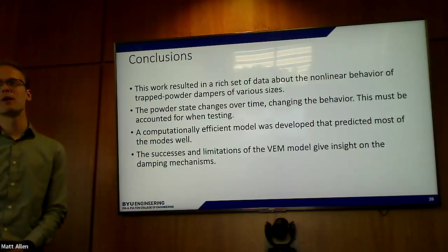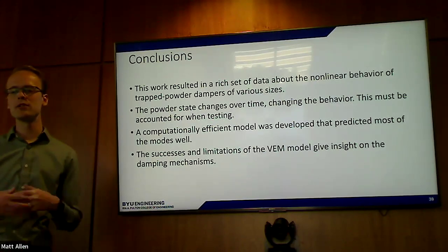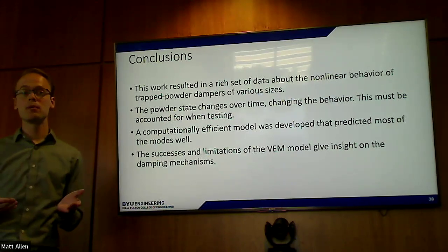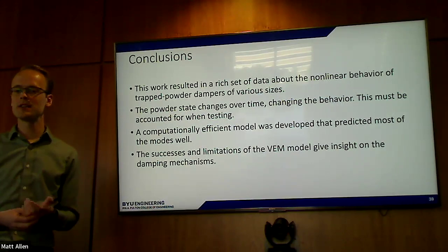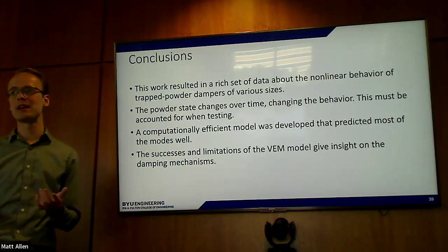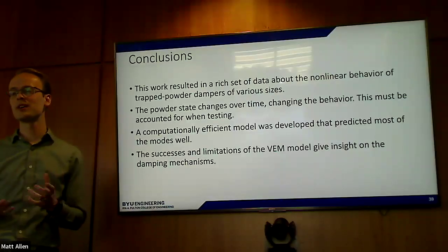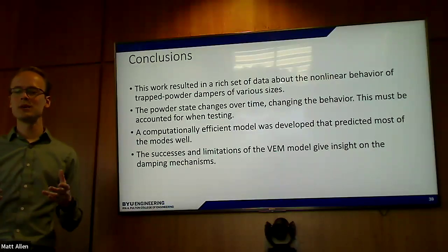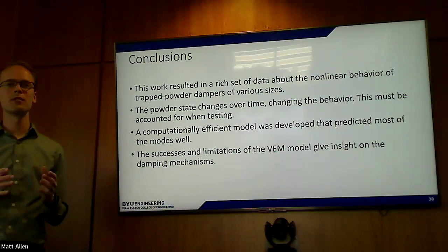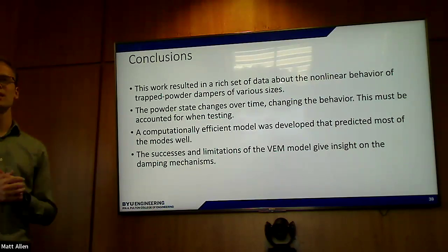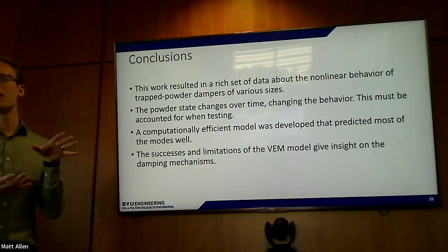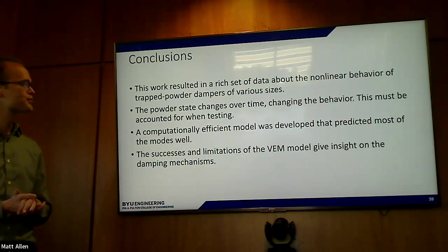In the worst case scenario, imagine you make a part and you test it and you measure it to have 1% damping, but then you take it out into the field and 6 months later, the powder is settled and now it has 0.1% damping and then it's vibrating 10 times as much. So we really want to make sure that people who are designing these parts are aware of this time varying component that the system can change over time. So you need to make sure that you capture the upper and lower bounds of the behavior.